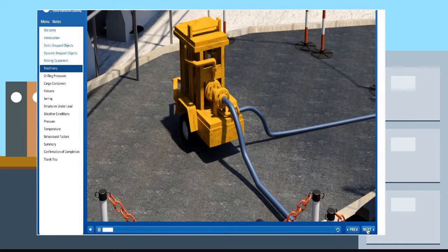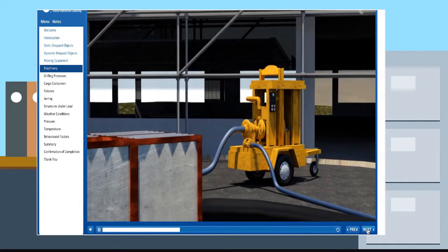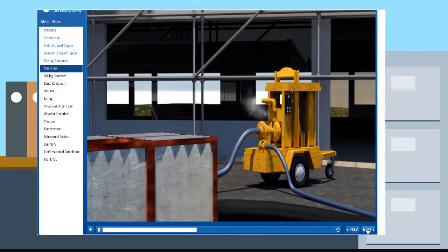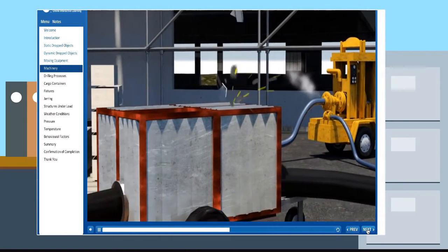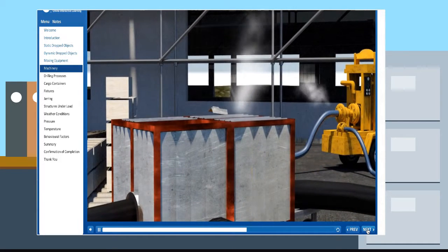Even if moving machinery or equipment is operated normally, there is the potential for parts to be propelled. For example, rotating equipment can cause vibration, which can work loose parts and even guards. Good inspection and maintenance practices must include looking for the potential of objects being propelled during normal operation as well as in the event of malfunction. These should also cover the potential for other equipment to be struck due to being in the line of fire.